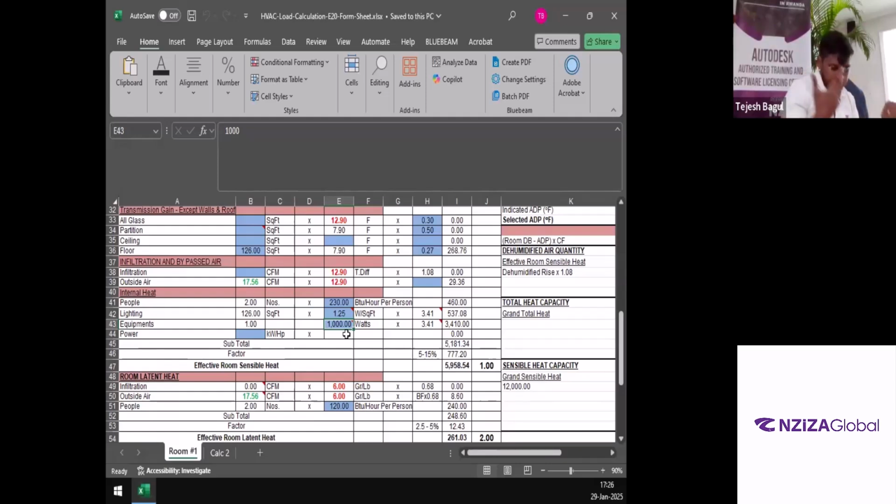Okay, we'll take an example of this projector over here. The energy that is being input into the projector, I think it's somewhere around 5 ampere plug over here. The voltage in Rwanda is 220 volt, correct? So 5 into 220 into, let's say, 0.8 power factor, right? That will be the energy that is being consumed by this particular projector.